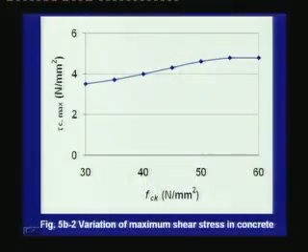The tau c max is given in the form of a table, and when it is plotted, it looks like this: for different grades of concrete, the tau c max slightly increases and more or less stabilizes when we reach a concrete strength of 60 Newton per millimeter square.